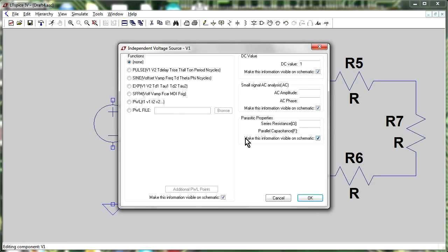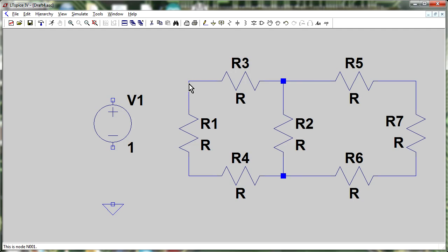But if we go into the Advanced tab, you can see that's not just a voltage source, but we can have not just a DC voltage source, but it can be a sinusoidal source, it can be a pulse source, it can be a piecewise linear source, and all sorts of stuff. But we're just going to use it as a DC source in this one. And we can just wire that up, and it's pretty easy to draw your circuit like that. And once again, you've got to connect that ground to some point in there. But bingo, we have a simple circuit.